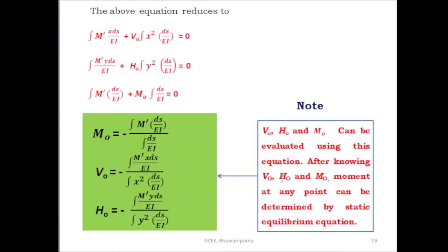Then after knowing VO, HO and MO, the moment at any point can be determined by the static equilibrium equations. So after knowing VO, HO, MO, you can find the moment at any point using the static equilibrium equations.